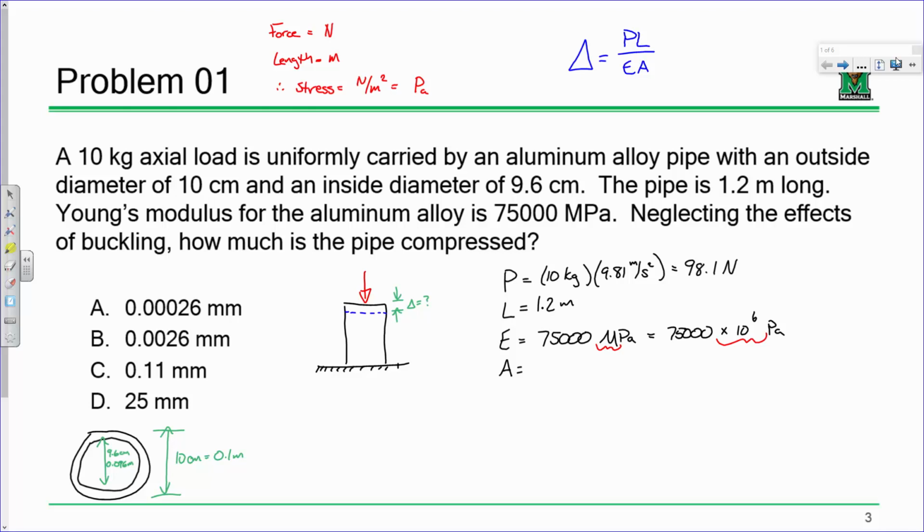Remember, when we say area, this is what we mean, okay? Remember what we think when we think cross-sectional area. This is how I define it: samurai sword or lightsaber, right? Then imagine taking that member, sticking it in a bucket of paint, and then sticking it on a piece of paper. What's the piece of paper going to look like? It's going to look like this little ring, right? And so how do I determine the area of that little ring? It's the area of the big circle minus the area of the little circle, right?